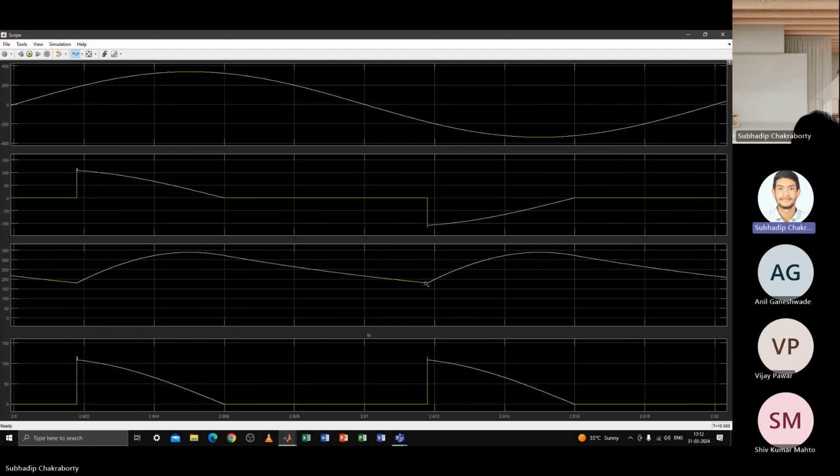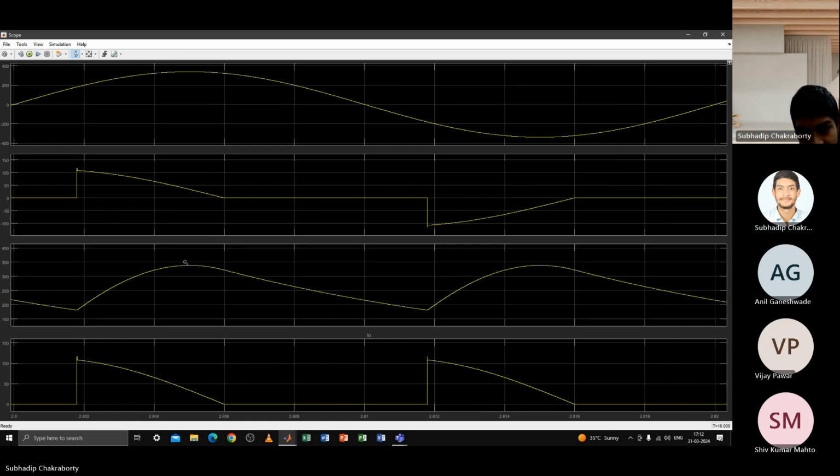Yes, this waveform is not in line with the sine, right? There is some non-linearity, and that non-linearity is also reflected in the input currents. So the main reason is the difference in time constant of the charging and discharging paths of the capacitor, which leads to the shift in this waveform. Because in DC you cannot say that since a capacitor is connected it will be a leading power factor; that flavor does not appear here. The main reason is the difference in time constants of the charging and discharging paths during one positive or negative cycle of a full sine wave. That's why this crest is appearing not in line with the sine.